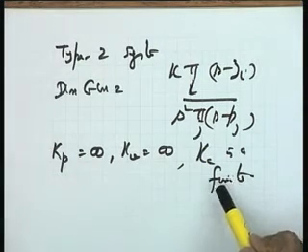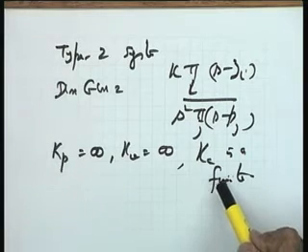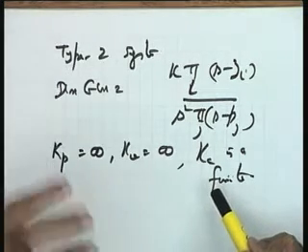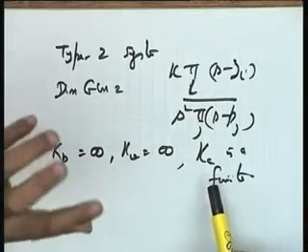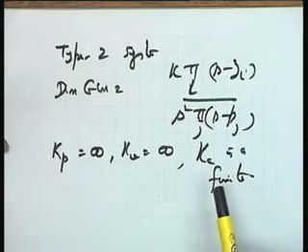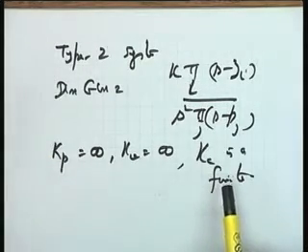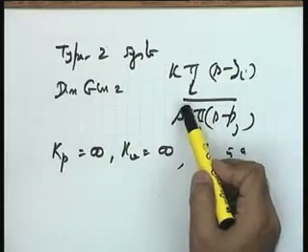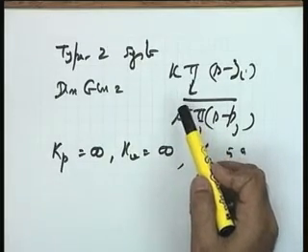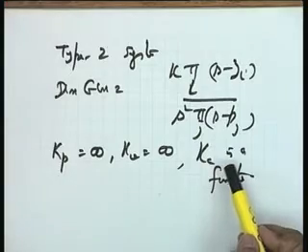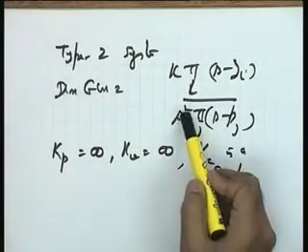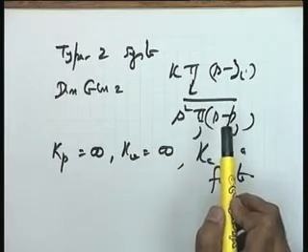Now, you fit in the argument I gave for the antenna position control system. If you want the error to be 0 for acceleration types of inputs also, in that particular case you will like to go for one more integrator, and hence it will become a type 3 system. And such applications are rare, very few, wherein you require 3 integrators in the forward path.